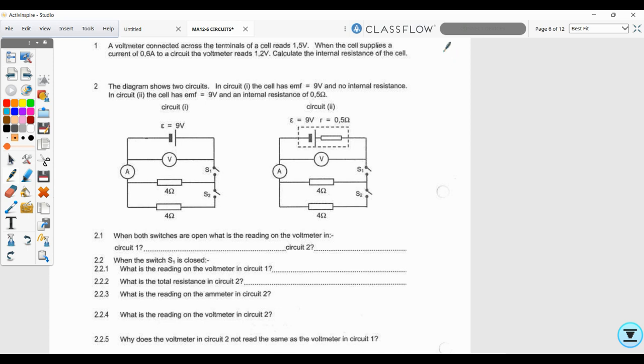when you do this test, please remember that V equals IR is your most valuable equation. But you can only use it if the V's and the I's and the R's are for the same thing. So if they say calculate the internal resistance of the cell, you can use V equals IR if that is the little r. With me? And you must just make sure that this V is the internal V. So if this is internal, then this is internal, and this is internal. They must just all be the same. You could always use V equals IR, as long as it's for the same thing.